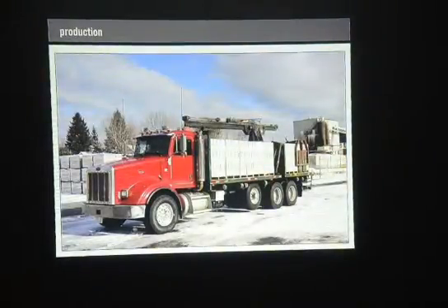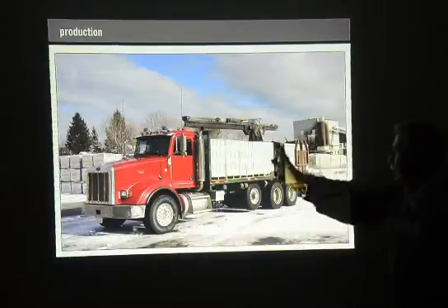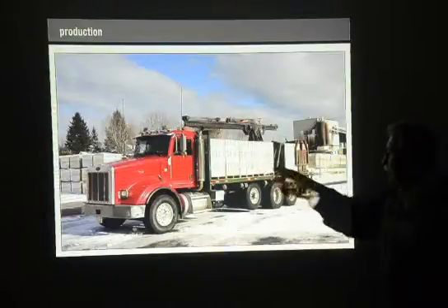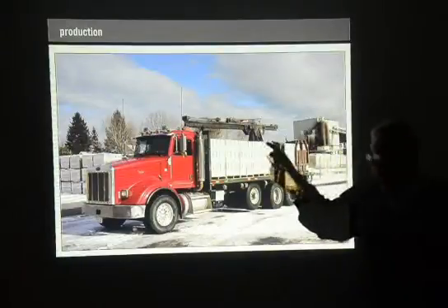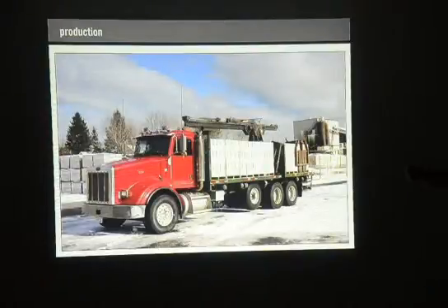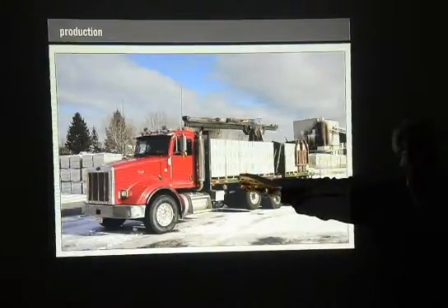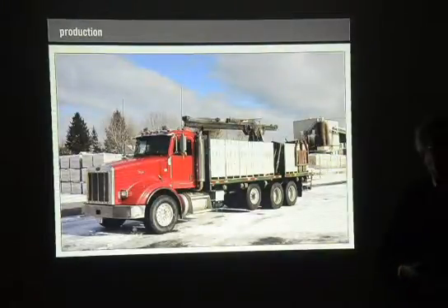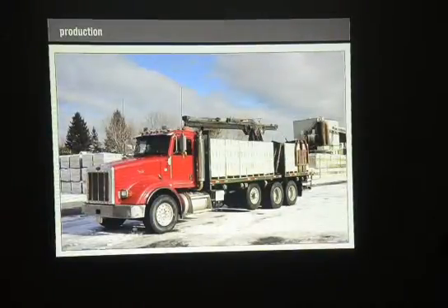Then the truck is going to mount them and make sure that they're tied down properly before they ship them. And if you were wondering, how many blocks can go on a pallet? I'll tell you. If we go with the standard block, we mentioned 8-inch wide, 8-inch high, 16 inches long, we're going to get about 90 per pallet. So if we have a larger size, like say 12-inch, we're going to get less than that, okay? So just thought you might like to know how many blocks per pallet.